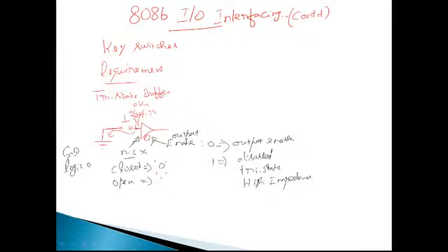So this kind of inference is now made. Now our challenge is to take this appropriately to the microprocessor data bus. And then this device should be addressed as well. So how do I take this particular thing? I can simply connect it to the microprocessor, to any of the data lines. So for example, let me connect it to AD0.